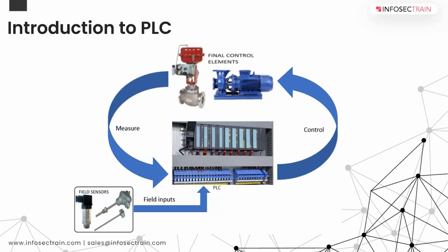So PLC is a digitally operated device. Basically, we can improve the accuracy and speed of operation by using a PLC. PLC would take inputs from various devices and so on. At the heart of a small system, this is what the majority of small to medium sized manufacturing facilities use, based on the number of IOs.